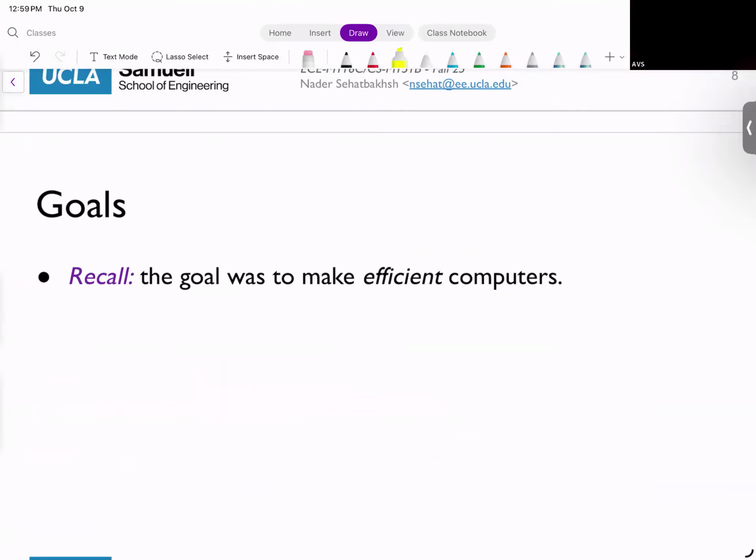The first thing that you can do is doing what we call multi-cycle. Multi-cycle design is when you are dividing the CPU into multiple stages. You don't wait for the entire thing to finish, but you say, for example, reading a register is one stage, and I clock it. So I separate this from the memory, from the ALU and so on and so forth. So I divide it into stages and then do it separately in each stage.